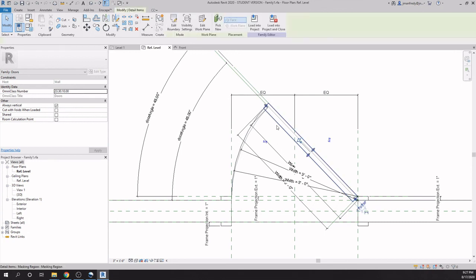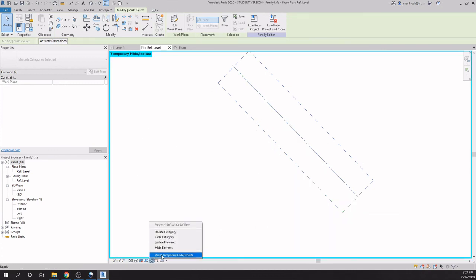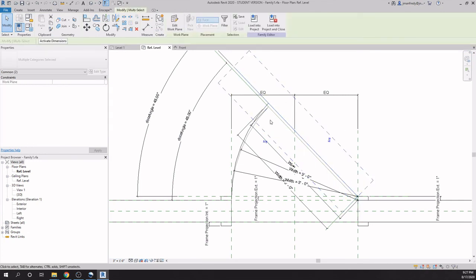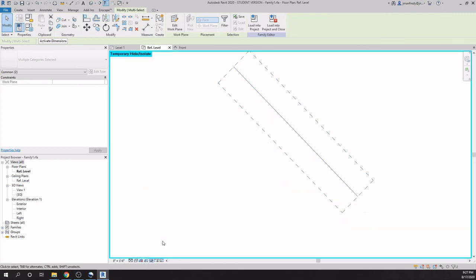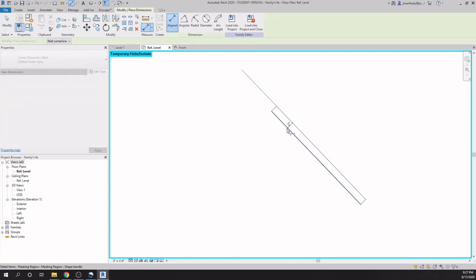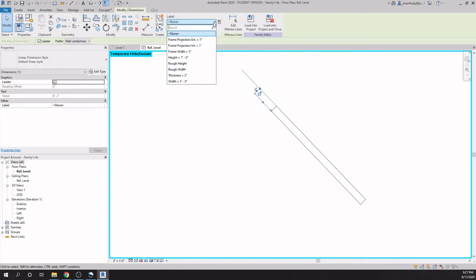So I'm going to grab that door and this reference plane using control, and in here I will isolate those two. This, control, and this. Okay, there. I need to have a dimension from this line to this edge of the door to control its thickness, which we know should be called the thickness parameter. So I need one more dimension, from this line to this edge. That, escape, that should be controlled by a parameter called thickness.